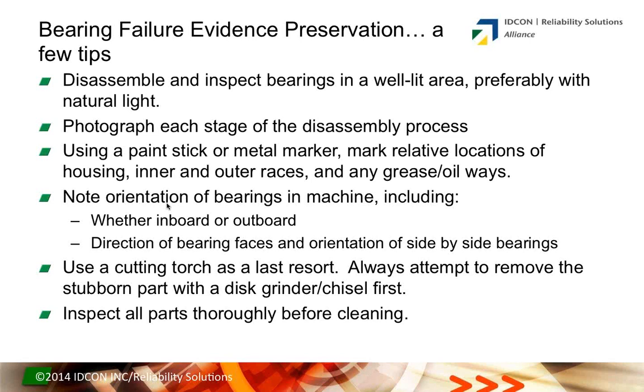And even though I'm fully attuned to looking for evidence, if I've photographed the disassembly and then a few hours or a day later I go back and look at the pictures, I'll almost guarantee I'll see three or four things in the photographs that I didn't actually see live. So it's very important we photograph the disassembly.